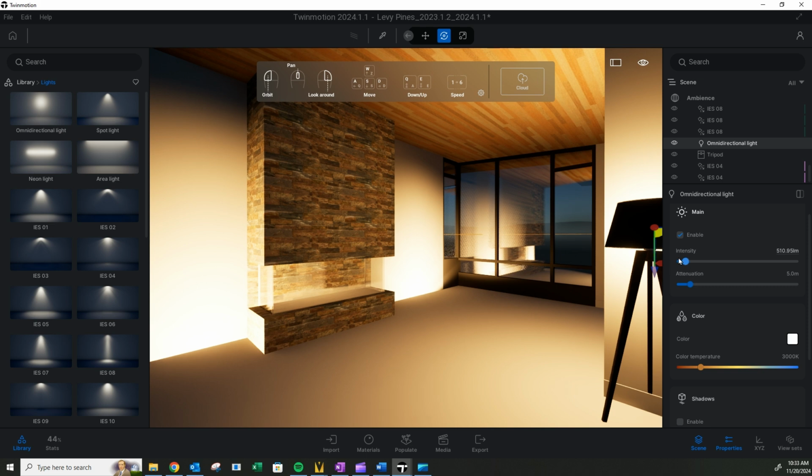If you put it on lighting control, whether that's line voltage dimming, you've got to look at the light source that you're using and its dimming capabilities. Some only dim to 10%, which isn't very much. Some dim to 5%, and quality ones dim down to 1% or lower. Some even dim to off. You can do line voltage, which would be ELV or triac dimming, or some of them are 0 to 10 volt. Most of the time, commercial fixtures are 0 to 10 volt. But if you're trying to do something specific, sometimes that's the only option you have.